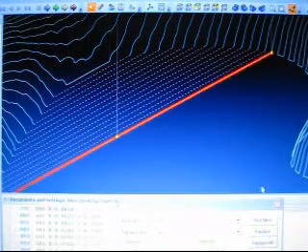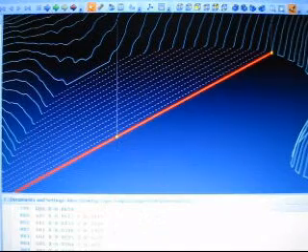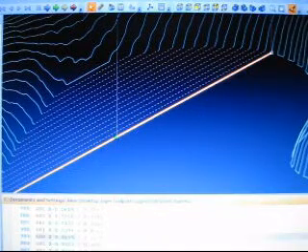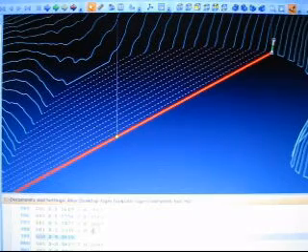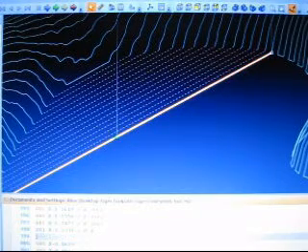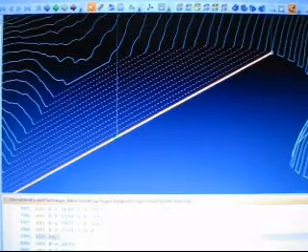Now all we got to do is insert a couple lines of code before and after that line. So this will give us our clearance. I'll enter in a space. I'll put a G00 and clear it at a Z at 0.1.